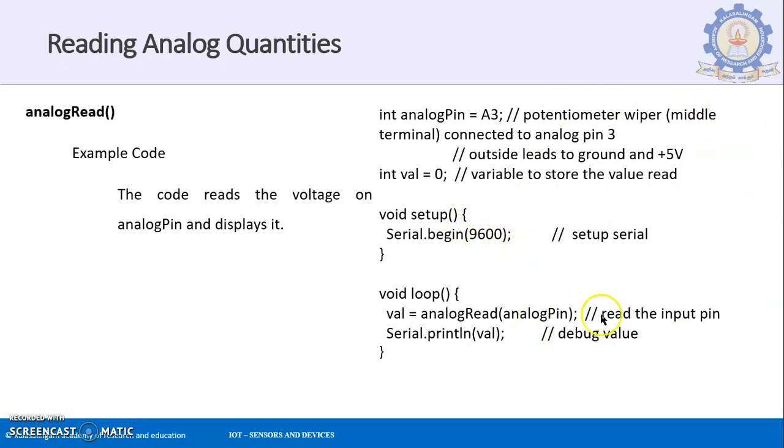On the serial monitor at the bottom right corner, you will also have the option of baud rate. Make sure that the baud rate over there is also at 9600. And what is happening next? This is a one-time execution. The initialization process has taken place over here. From the pin A3, I'm going to move the value to this serial monitor. So the variable used for that is value.